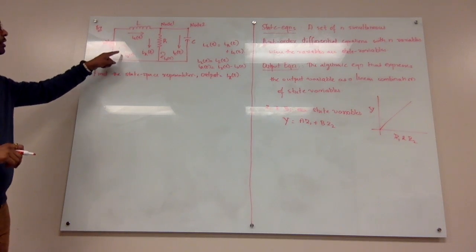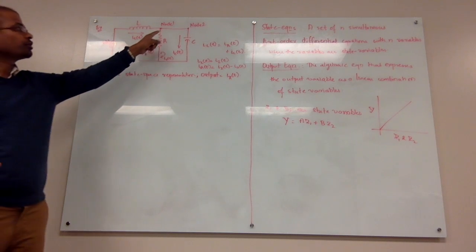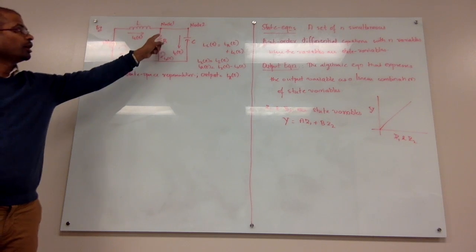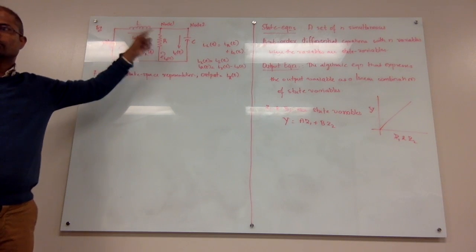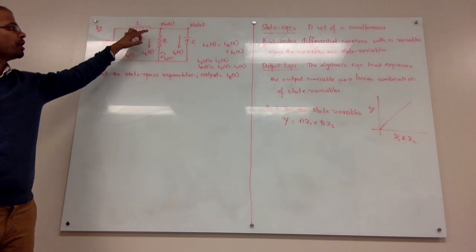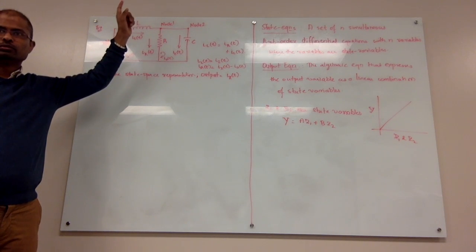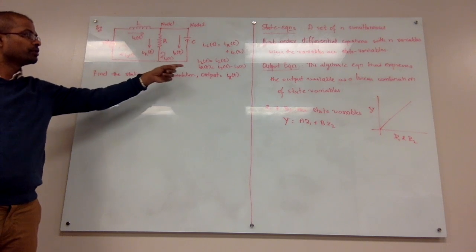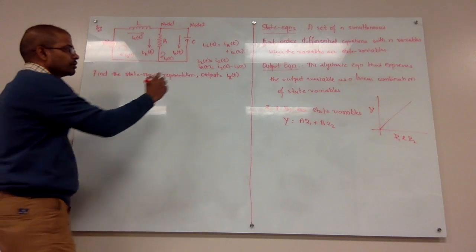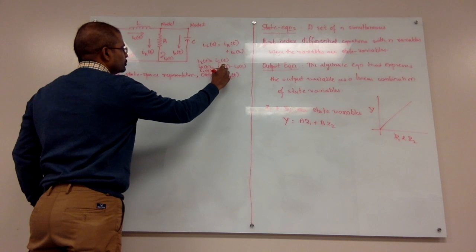You should understand, this means that current I1 is flowing like this in mesh 1, and I2 is flowing like this. Both are flowing clockwise in each mesh. So IR has to flow like this, going up, and IR would be I1 minus I2. What would IC be? IC would just be I2.